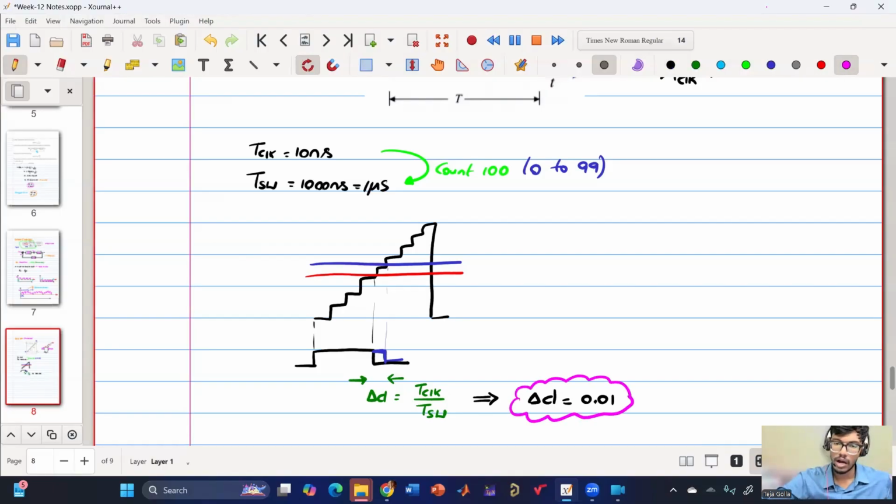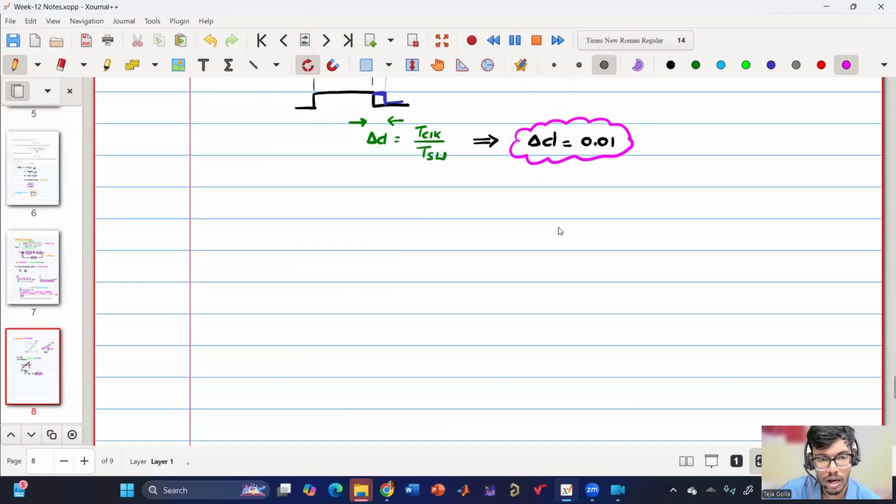So now I have finite resolution vertically in terms of control voltage and horizontally in terms of duty ratio, which are infinite in the case of analog control. So in the case of digital control, because of the quantization, both vertically and horizontally, I have limitations in the smallest incremental value of the control voltage as well as the smallest incremental value in the duty ratio. Are these two things clear? How we are correlating the vertical axis as well as the horizontal axis? Yes. Yes.